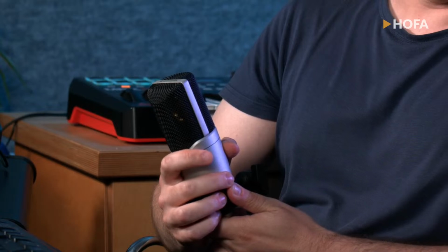So first of all, when we talk here, it's audio events that are going on, because you can hear my voice when I talk to you, and I could use something like this, which is a microphone. When the microphone is connected with our preamp, with our interface, with our device, whatsoever, a mixing desk or something that can work with audio, there will be a conversion. So we will have electricity going through the microphone, and at some point after the preamp stage, there will be a conversion. Our analog signal will be converted and we'll have a digital signal.